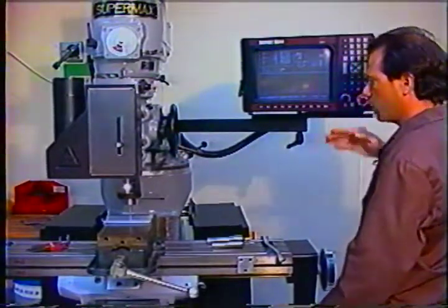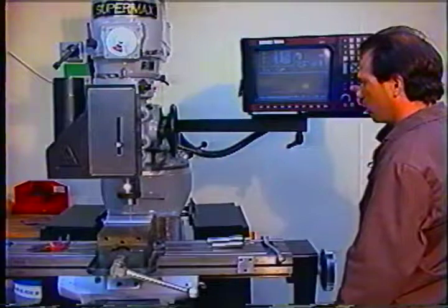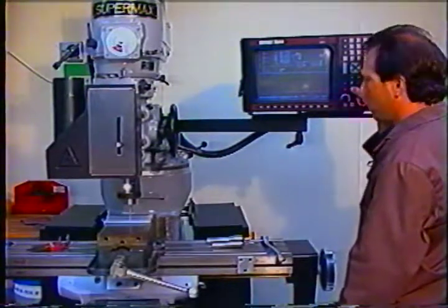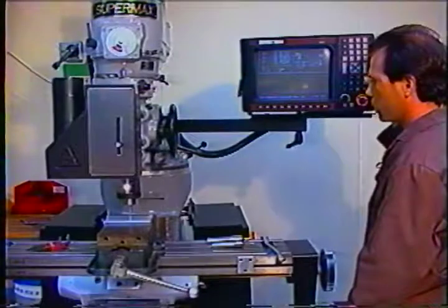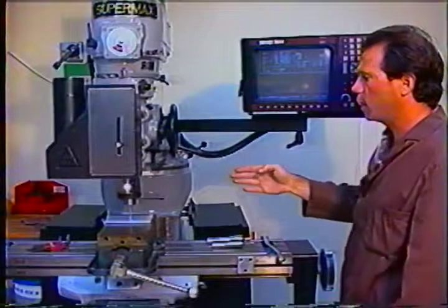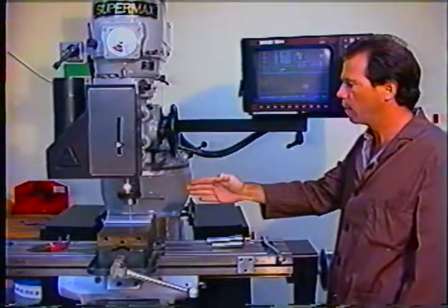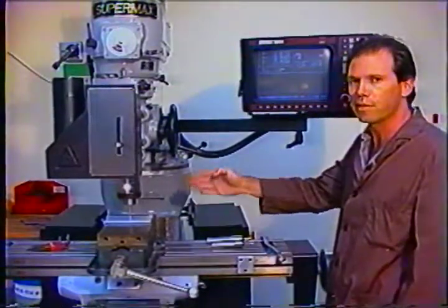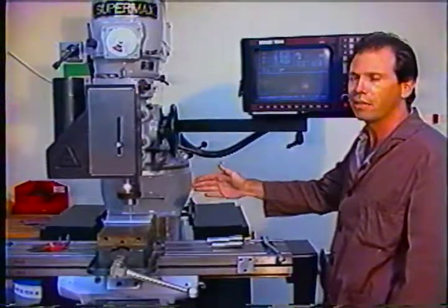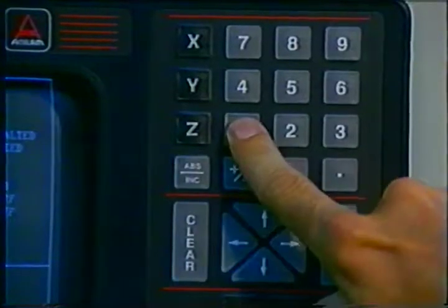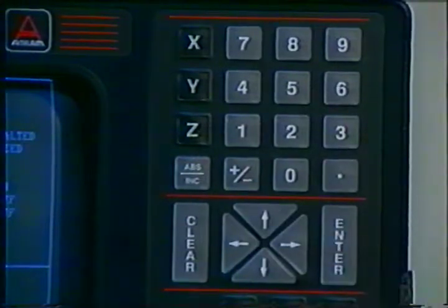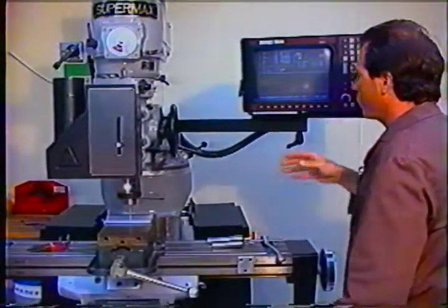I moved a little too close, so I'm going to back off and switch to 1 thousandths at a time. And there the edge finder just kicked out. Spindle off. At this point, I know that I am sitting 0.100 inches positive to the positive side of Y0. So I touch Y.1, enter, and the display changes. Now we've set both X and Y.